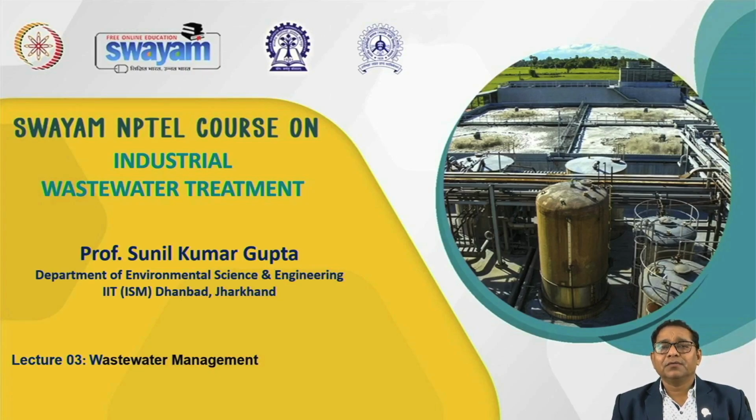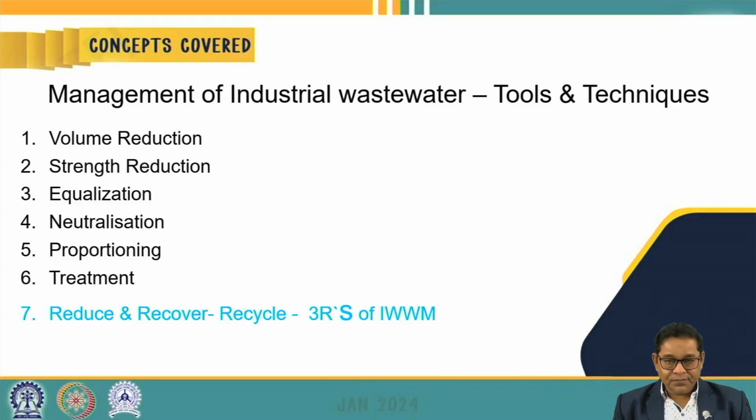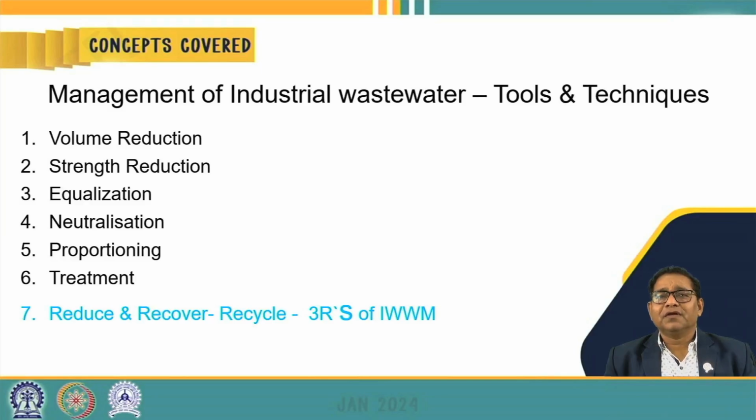So today we are going to deal with a completely new topic, on the various tools and techniques, the important key elements of industrial wastewater management. Broadly, the tools and techniques used in management of industrial wastewater involve volume reduction, strength reduction, equalization, neutralization, proportioning, and then treatment. Basically, there are three R principles that we use: reduce, recover, recycle.